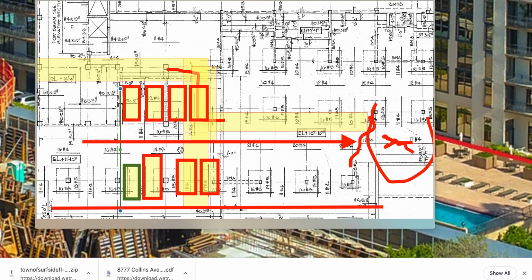Like I told you, you can reinforce it with steel coming across here. But ultimately, so what, you reinforce it, and this doesn't deflect at all. Say you get it so tight with steel that it doesn't deflect at all. It still has to carry its load down these columns, carry it over the columns. This load, it couldn't do it. So it breaks free, punch shears away from it, right? It punch shears away from it, yeah, great.